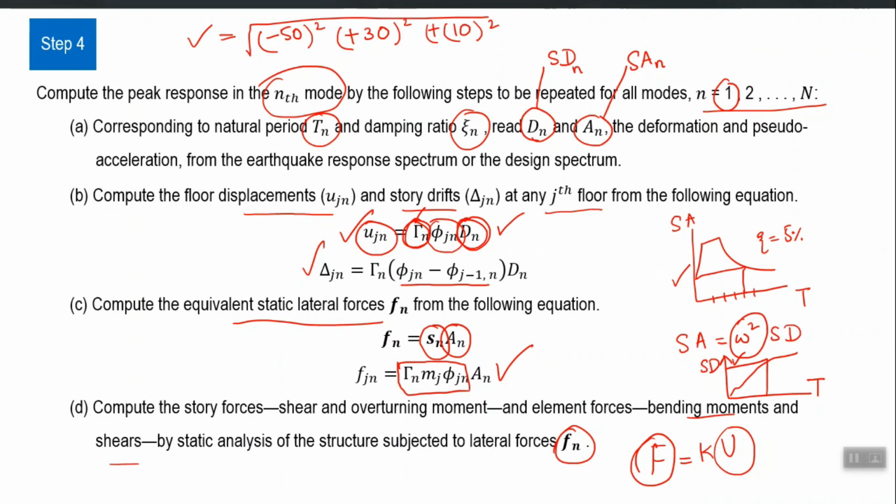Although it is not based on the mode shapes idea, since it is calculating the response for each time step, if at one particular time step it is positive and then it goes to negative, it accounts for that reversibility or change in direction of the response. RSA does not account for the change in direction of response.